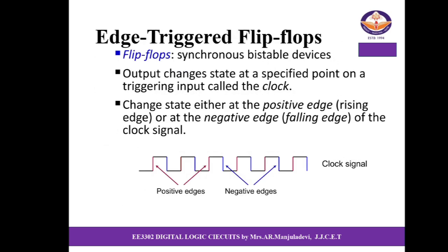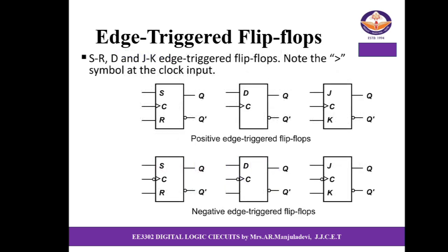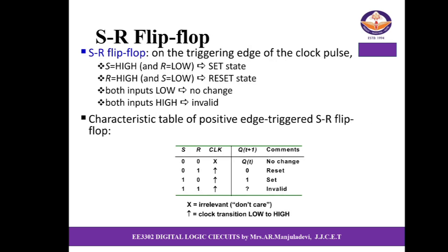Next, edge-triggered flip-flops. Flip-flops are synchronous bistable devices. The output changes state at a specified point on a triggering input called the clock. They change state either at the positive edge or at the negative edge of the clock signal. These are the timing diagram and the logic diagram of edge-triggered flip-flops. The clock input is given directly for the positive edge, but for the negative edge, a NOT gate is used in the clock input.